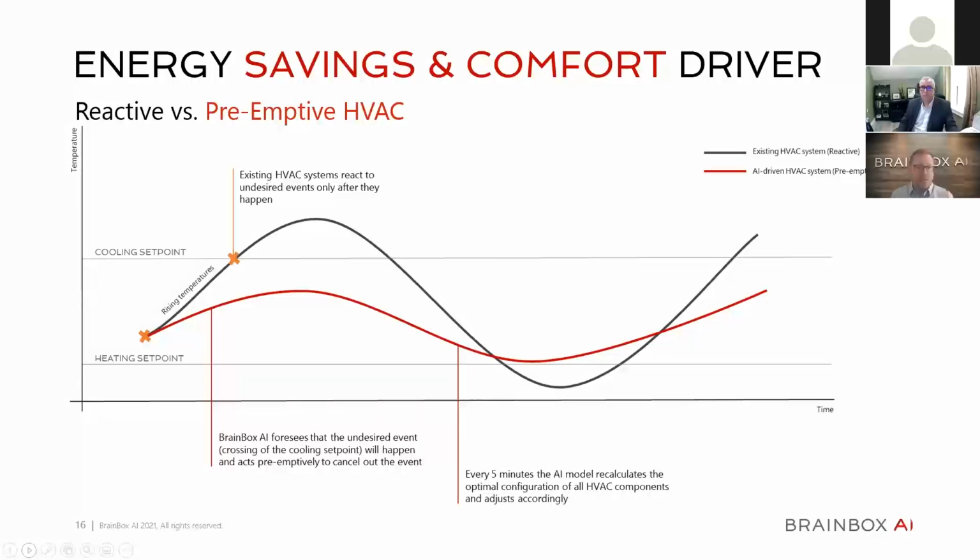So it's like, okay, I need to start cooling, so I need to open up my VAV damper, the air handler turns on second stage of cooling or opens the cooling valve more, and you're blowing colder air into that space. But often you've already lost the thermal momentum of the space, so you have to overdrive it to get it back down. Then you go into this constant sine wave function. This is really causing a lot of comfort issues for clients and students and everyone.